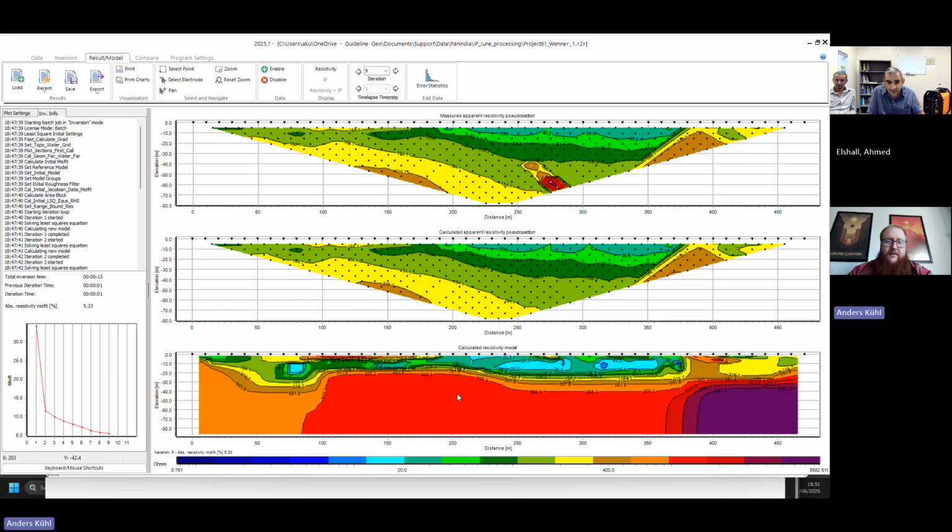Is there water in it? Yeah, so it could be saturated. Yes, most probably it will be saturated, not like other parts where it will be dry. So then it will be highly resistive, mixed with whatever it's saturated with. Fresh water is usually also resistive, but it will definitely be more resistive than the clay and sand. But that's essentially the theory of ERT.